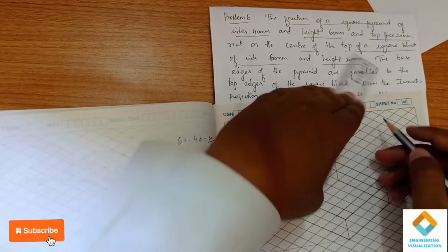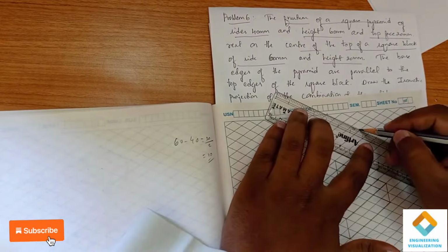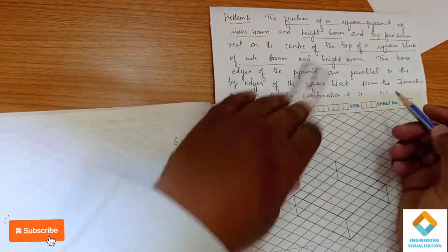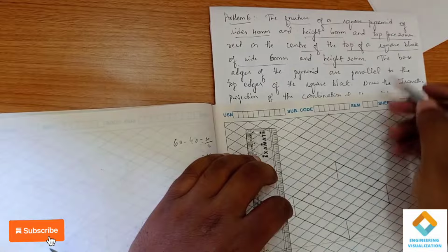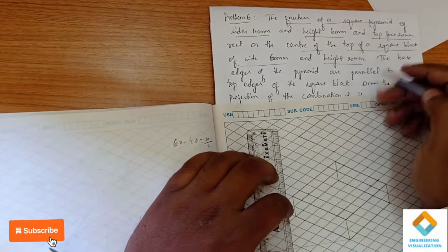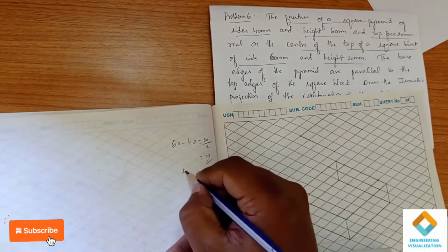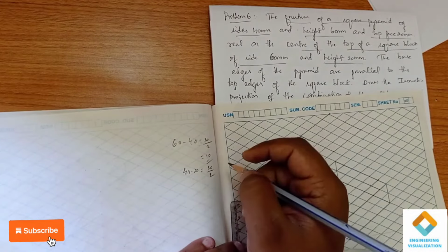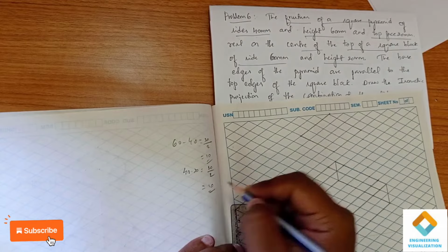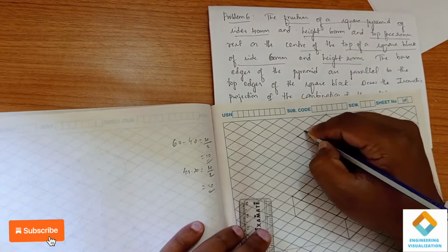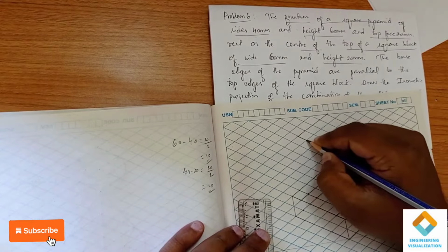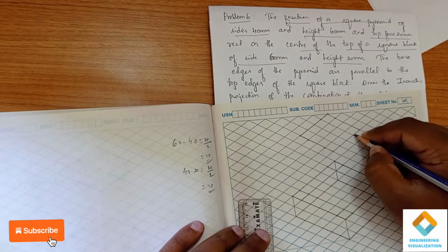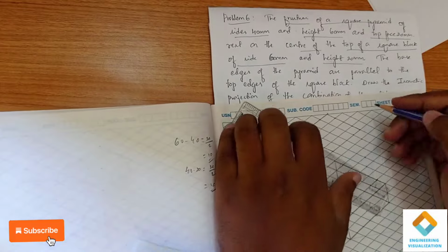So we have to construct a frustum here. Okay, you construct here a box of another 40, but for the top face we require a box of 20. It's again the subtraction of the box method. So 40 minus 20 is 20, on either side means divided by 2, so we get 10. So subtract by 10 on either side.